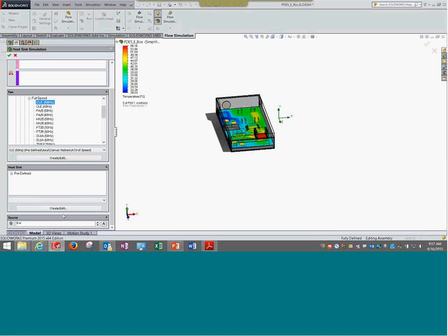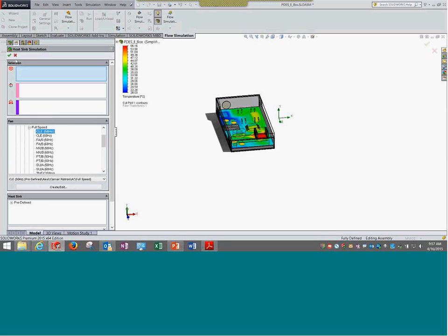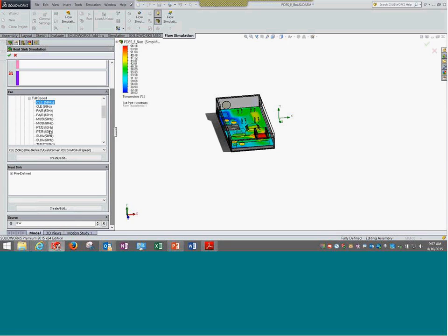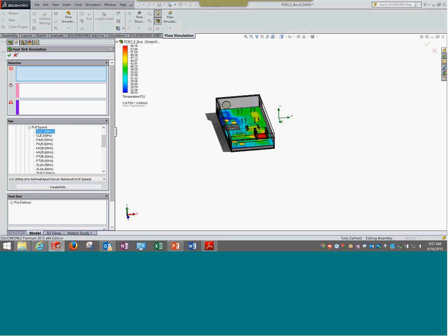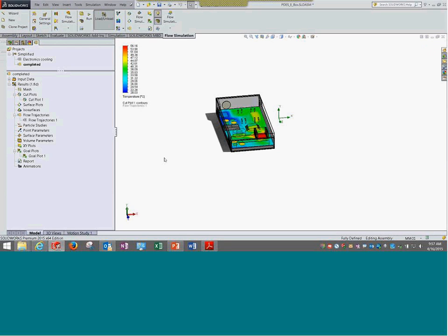There are heat sinks which you want to simulate, nothing wrong, you can do it. There are also scenarios, if I put it in a different way, where there will be a chip which is producing the heat. Right above the chip, there is a heat sink which sits, and above the heat sink, a fan is sitting. There is an entire package sitting at a certain location, and that system works. Now, instead of creating all three, that is the chip, the fan, and the heat sink, it can be represented in a square block or a few different blocks, and that kind of setup can be created or used in the heat sink feature.